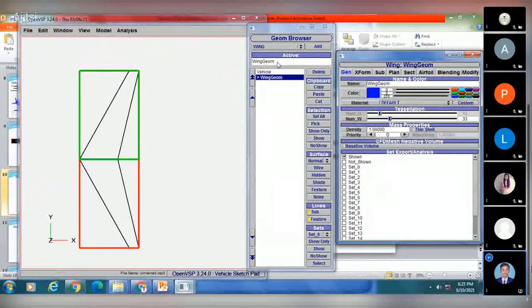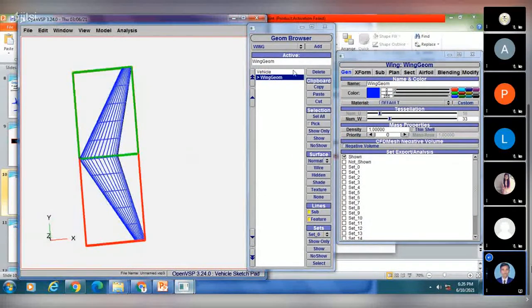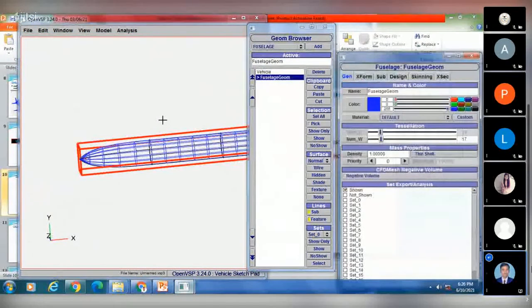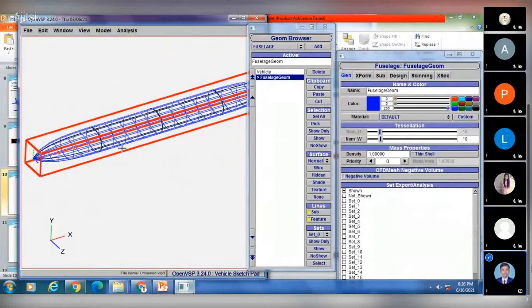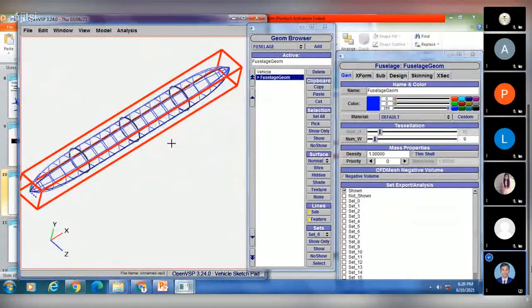Now next what we have is tessellations. Once again I'll change this from none to shaded. Let it be wireframe. I delete this and add visualize to show the tessellations. Now see, in this visualize, the number of u is 17. I'll change that to 10. Again I will change this to 2.